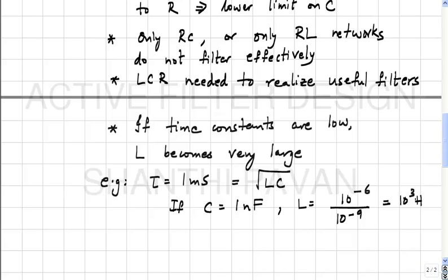So, in the early 60s and 70s, when people were trying to build telephone networks across America, digital telephony, that is where all this PCM stuff started happening. Then they had to digitize voice. The first thing to do was to take voice, limit it with a 3 kilohertz filter, because all the useful stuff that you say is there in 0 to 3 kilohertz. And then digitize it, and then do all this PCM and then muxing and switching and all that stuff, right.